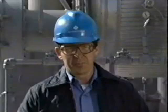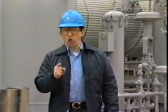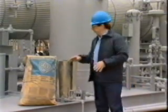For removal of dissolved contaminants, activated carbon filters are used. When the glycol contains measurable quantities of light hydrocarbons, the carbon filter must be changed or reactivated frequently. Most glycol systems cannot be operated successfully without carbon absorption. Now, there are two types of activated carbon filters. Small systems like this one use a carbon canister with replaceable cartridges. Larger systems use a loose-fill carbon vessel that uses granular activated carbon.